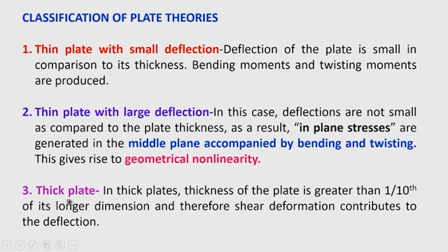Then the third theory is thick plate theory. In this theory, the thickness of the plate is larger, and it is generally assumed that it is greater than 1/10 of its longer dimension, and therefore, the thickness is significant, and the shear deformation contributes to the deflection.